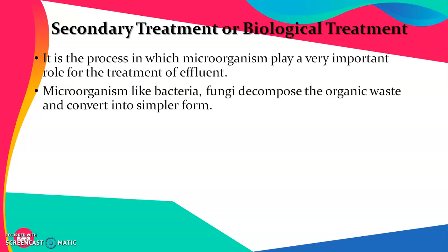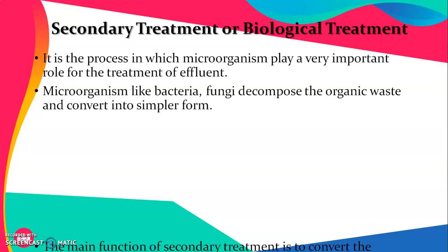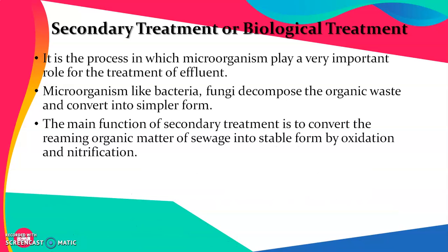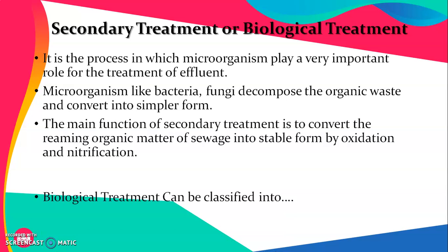Microorganisms like bacteria and fungi decompose the organic waste and convert it into a simpler form, which is far more acceptable for discharging the wastewater into the environment. The main function of secondary treatment is to convert the remaining organic matter of sewage into a stable form by oxidation and nitrification.